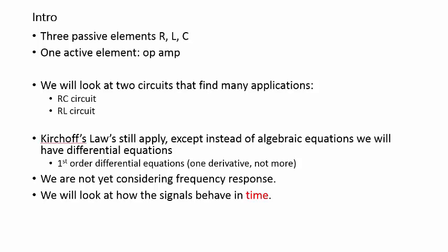So we are going to look at two circuits in this chapter that find many applications. One is the RC circuit, so that's a resistor and a capacitor together in a circuit, and the other one is an RL circuit. For these circuits, Kirchhoff's laws still apply. Kirchhoff's laws always apply, except that for these circuits, instead of having algebraic equations for summing the currents into the node or summing the voltages around the loops, we will have differential equations instead.